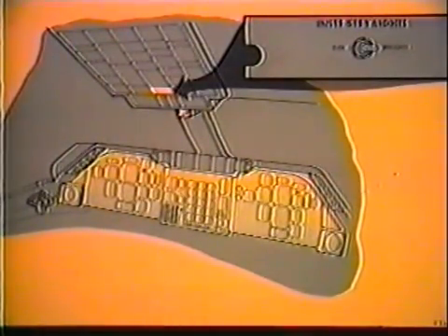The instrument standby lighting system provides panel illumination in the event of a power loss. When activated by a loss of the DC essential bus, the forward instrument panels, the standby compass, and the second officer's panel are illuminated. These floodlights will now be powered by the DC standby bus. The switch permits selection of either dim or bright.